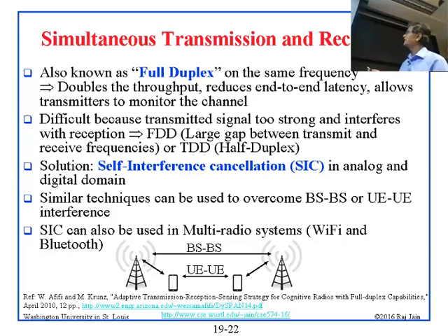It can be done in the analog or digital domain. Basically, you know what you're transmitting, so you subtract that out. Actually, when you use a full duplex speakerphone, that's exactly what you do: when you speak, you don't listen to yourself. Basically, the speaker cancels it out.